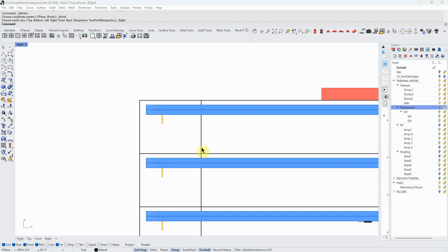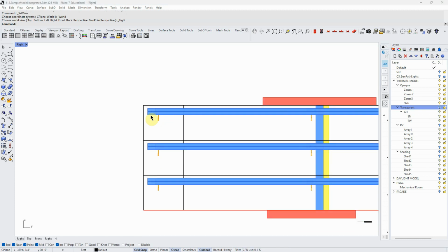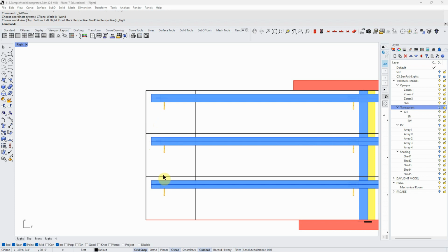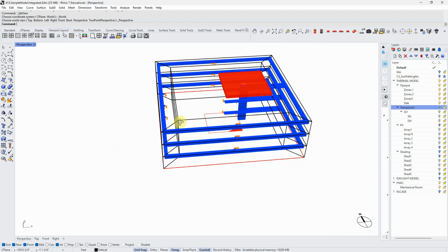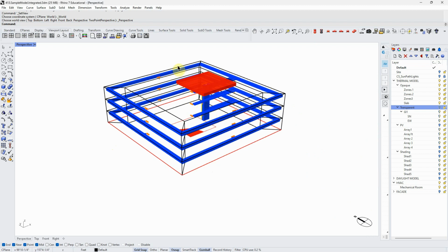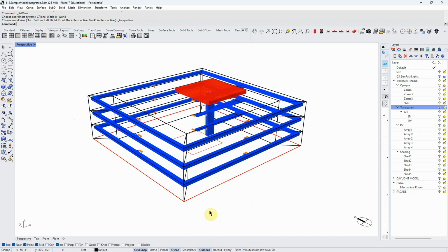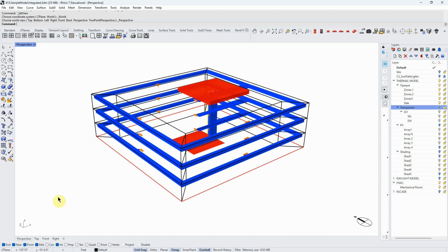So even with the same system that I'm looking at, if I change the aspect ratio, I'm going to change the ceiling height or the floor to floor height. And like I said before, that might make a big difference in terms of my design, even at an early stage. So that would be one reason I would do this right now. It's quick, it's easy, it gives us information for almost no time, which means no money in the professional world. So I think it's a good thing to do, and I would suggest you do it as a portion of your HVAC design for your final projects.